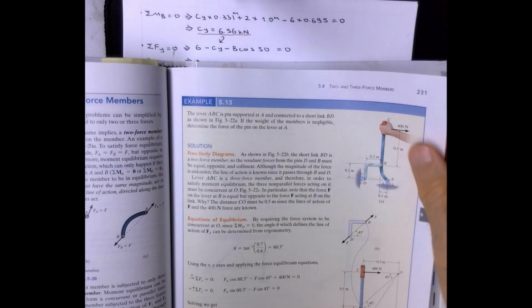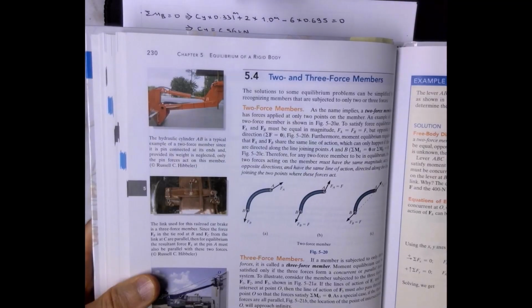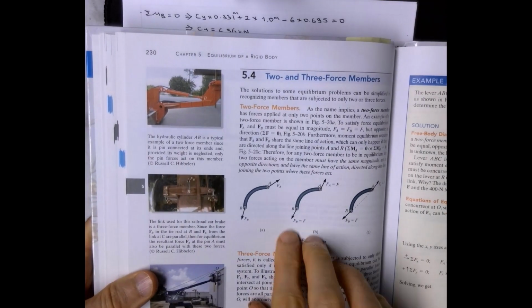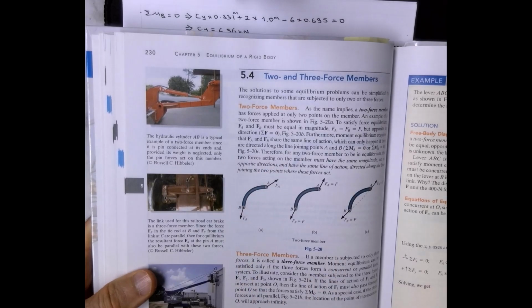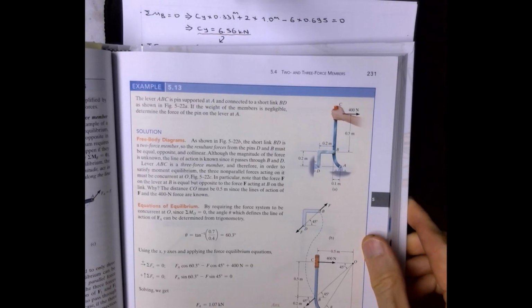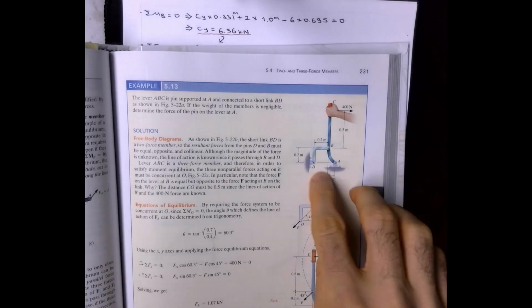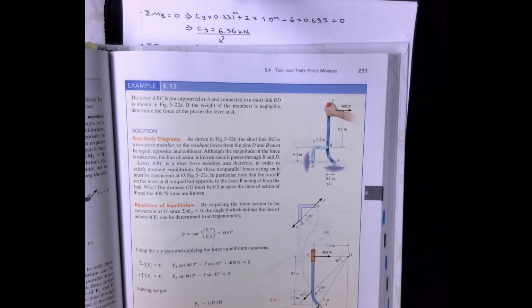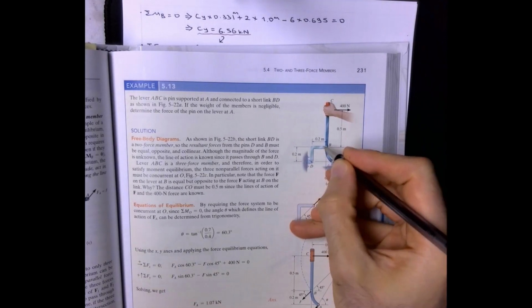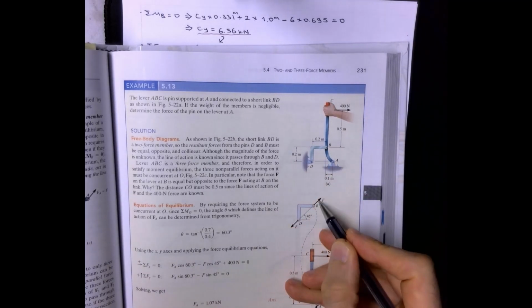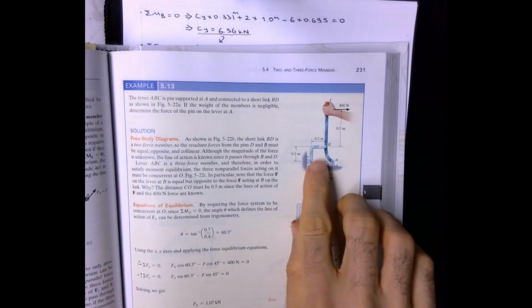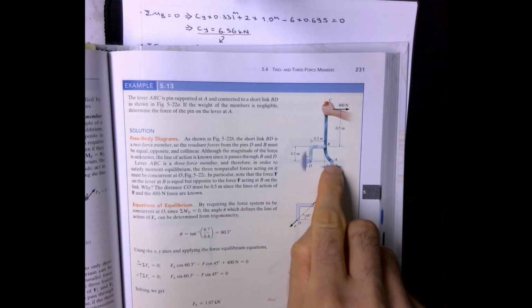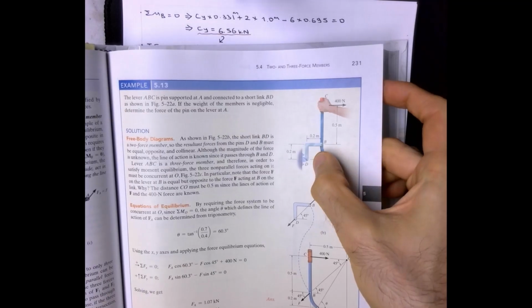And here you will see 2 force members. It's covered here. You can look at the narrative for 2 force members. Mechanical engineers, you would be dealing with machines, and I can immediately tell you that BD is a 2 force member, right? So if you connect these points, the resultant will pass through C. That's how you solve this. Otherwise, you won't be able to solve because there are going to be 4 unknowns. Very critical. You shouldn't be missing any 2 force members.